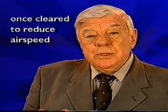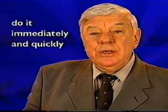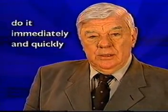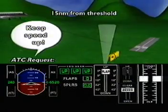Start with the idea that you must be stabilized on a 3-mile final. That means stabilized speed, configuration, and thrust. Once cleared to reduce airspeed at the pilot's discretion, do it immediately and quickly. Do not reduce speed slowly, because you may end up on a short final with high speed and reduced thrust.